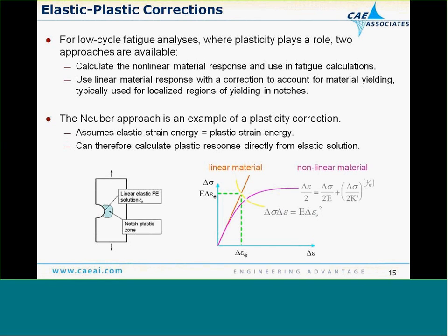I mentioned that you can have, especially for a strain life type of application, plasticity occurring, especially in local regions like notches. And there are a number of ways to account for that. The first way is you can actually perform a nonlinear material response in your finite element analysis and feed that into the strain life fatigue analysis calculation.